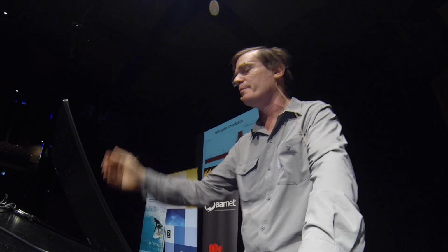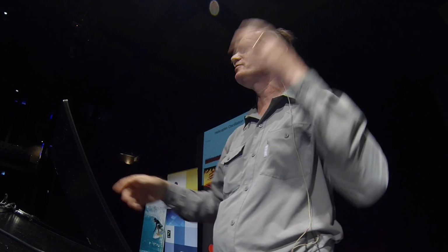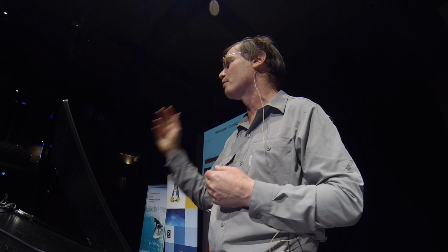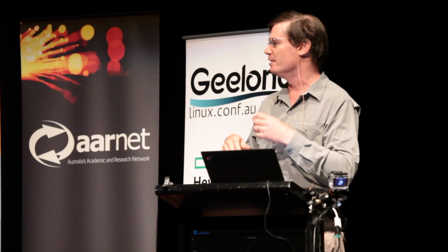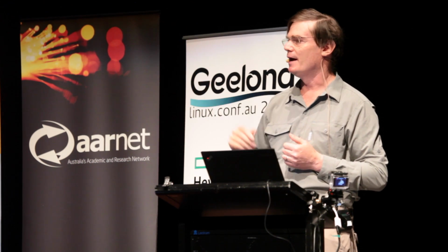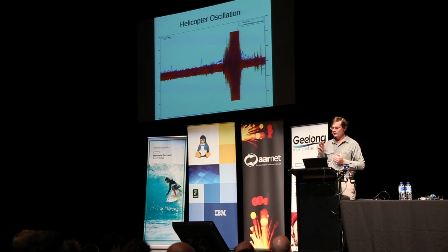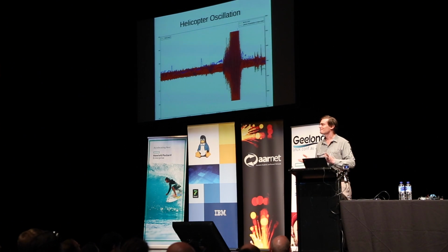Now what happens is that at that point, we're running a Kalman filter, which is basically a sensor fusion technique for taking all of the different sensors, the GPS and accelerometers and gyros and compass and barometer and laser rangefinder, and fusing them all together and trying to get the state of the vehicle, where it is and what its attitude is, right? And its velocity, etc. And the Kalman filter basically lost the plot, right? And it no longer knew which way was up.